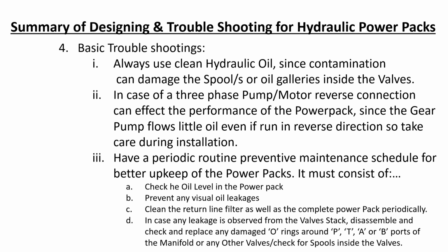Next, here we have given the basic troubleshooting. Always use clean hydraulic oil, since contamination can damage the spools or oil galleries inside the valves. In case of a 3-phase motor pump, reverse connection can affect the performance of the power pack, since the gear pump flows little oil even if run in the reverse direction. So take care during installation.